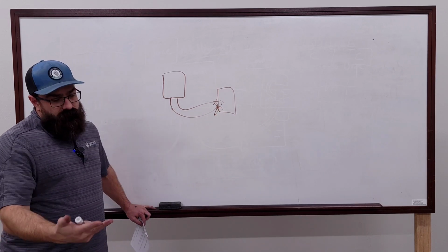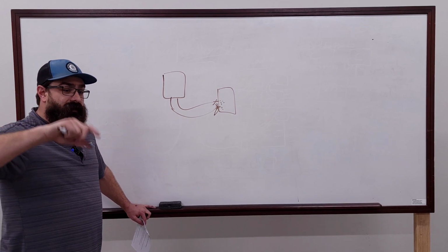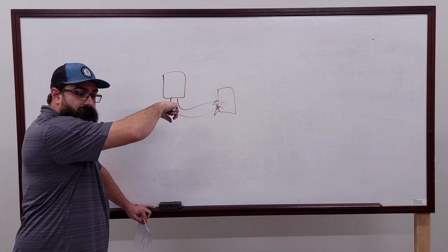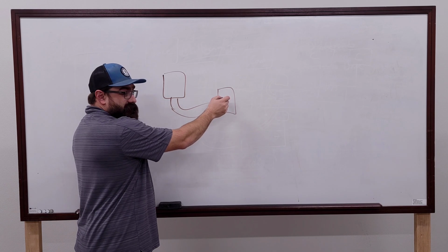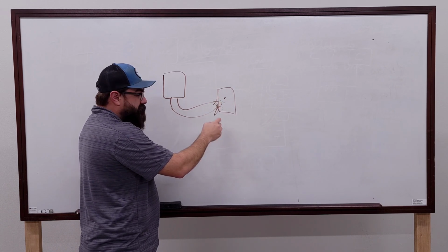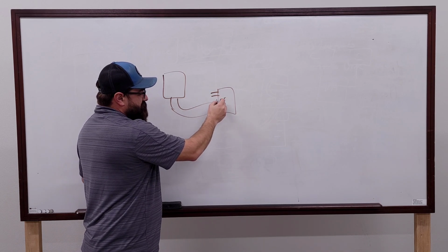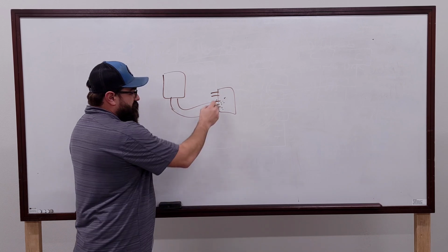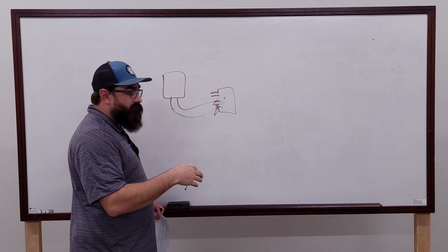I put 10 volts to, I get that, but that is a separate 10 volts, not something coming from the same panel. So there may be something somewhere else. It's not even involved with this SCR, right? Because all this SCR needs is that 0 to 10 to drive. It's got 24 volts powering it, and then it has a 0 to 10 input. This 0 to 10 input can be sourced from a completely different source, and you may not have that problem.